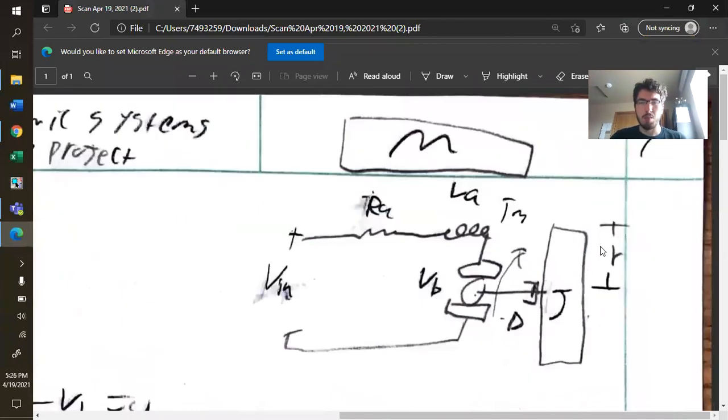We're modeling 1/4 of a robot with an electric motor and a wheel attached to it. So here's the resistor, the inductance, and the voltage drop VB across the motor and the V in. And we're calculating for a damping force, maybe in the bearings of the motors and whatnot. J is the inertia of the wheel, and r is the radius of the wheel. And M is 1/4 of the mass of this section of robot.